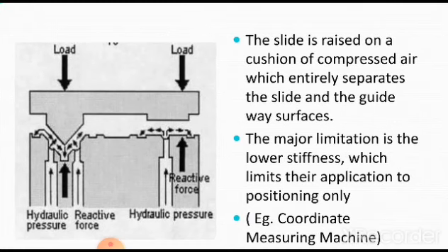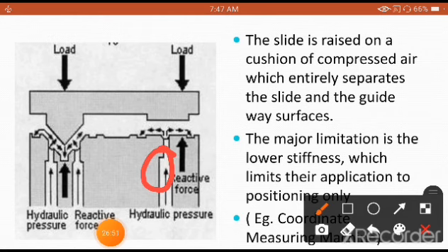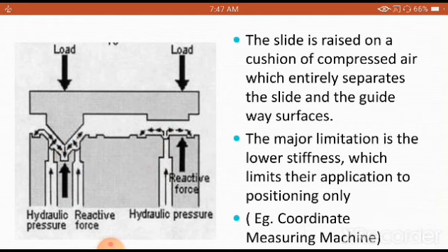So what we are going to do with the help of these inlets, which you can see very clearly here, is provide the desired amount of air pressure in this gap, which can give a cushioning effect and lifts the slide so that it will start moving, separating the guideway surfaces.